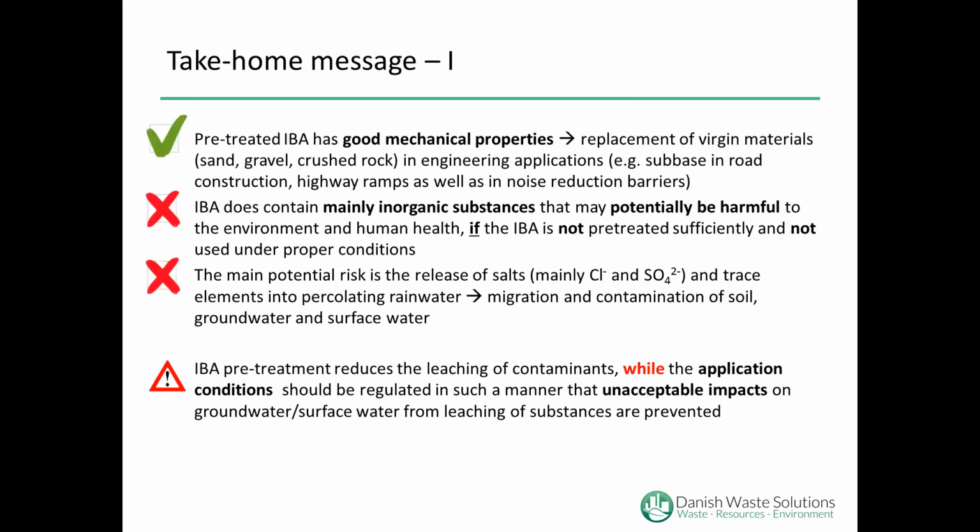So the take-home message here is that pre-treated bottom ash has good mechanical properties, and it can replace virgin materials in engineering applications, such as typically subbase in roads, maybe base in roads, highway ramps, and so on.